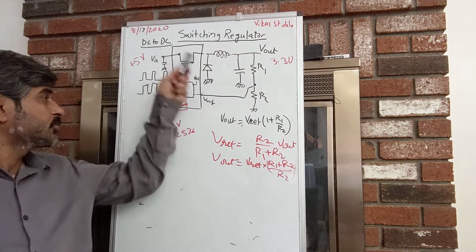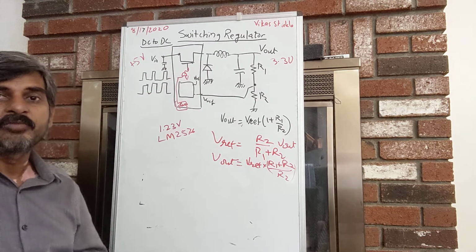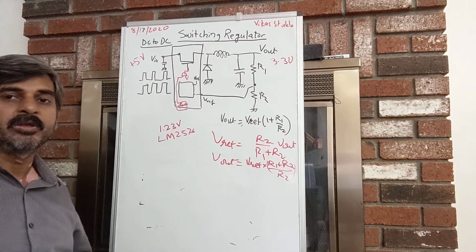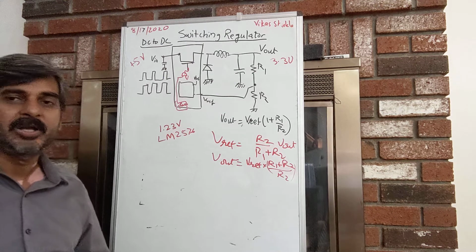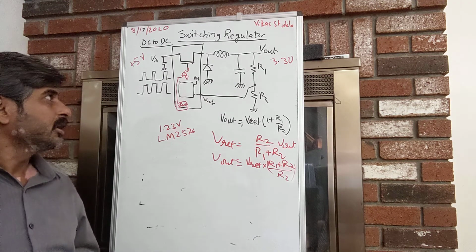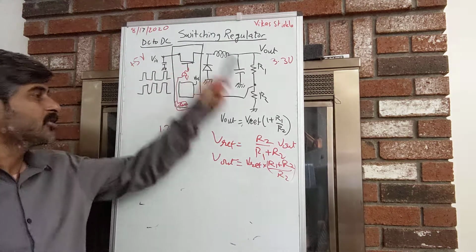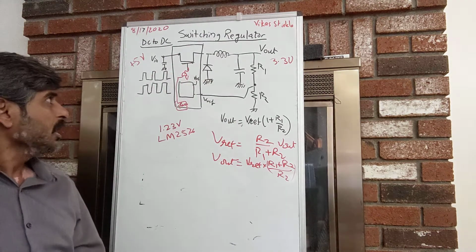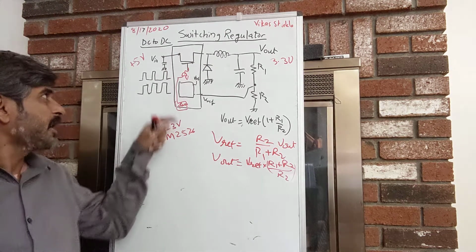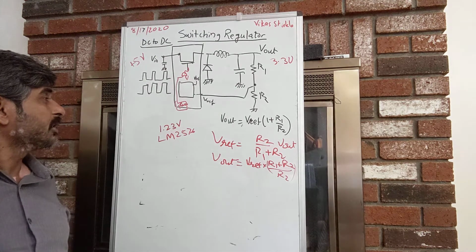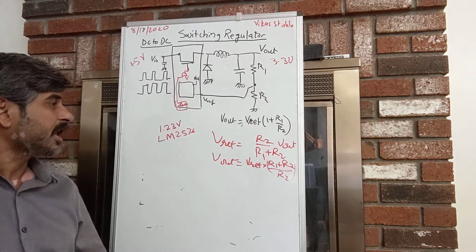The third thing that chip could be doing is to monitor the current and cut it off if the current goes beyond a certain limit, for example in a short circuit or anything like that. So typically a 3 ampere cutoff could be sensed by the internal circuitry and will turn the whole thing off. There could be other things, for example, in order to control the EMI or a stable loop gain, there could be some RC elements doing those specialized functions.